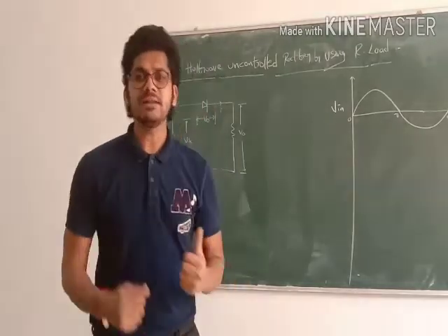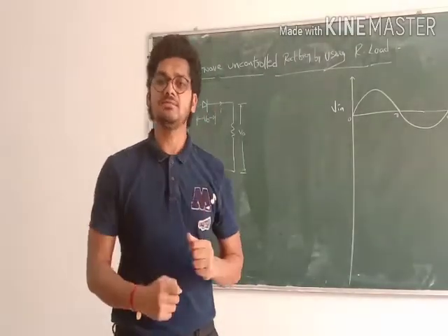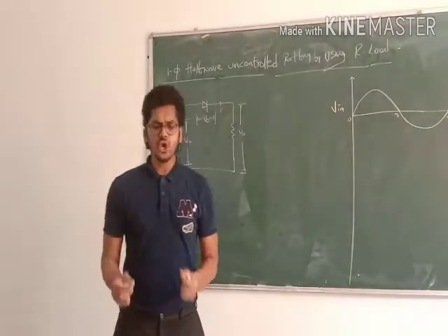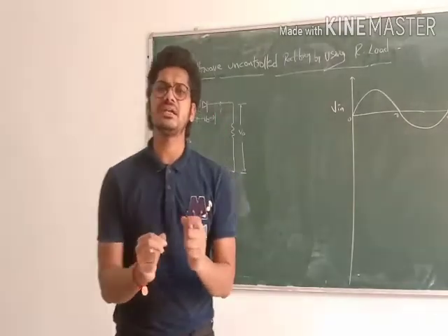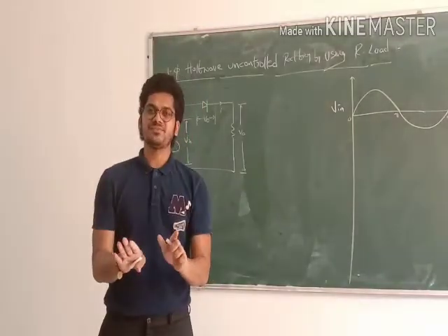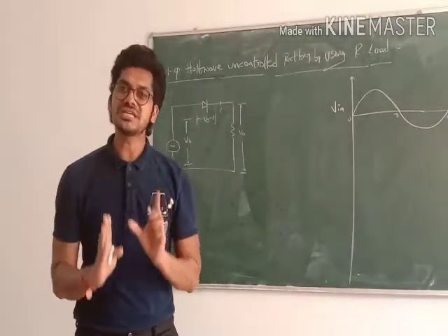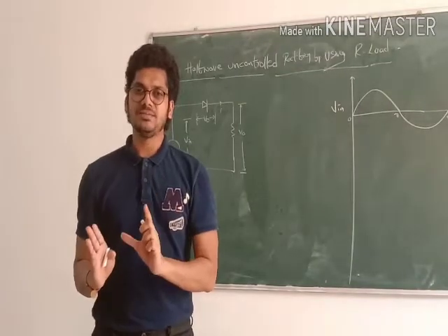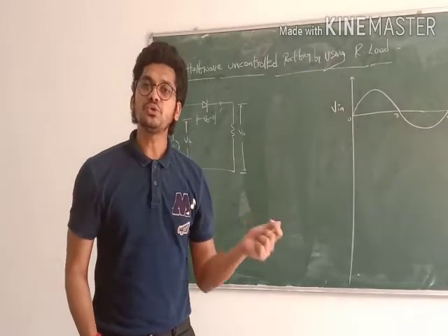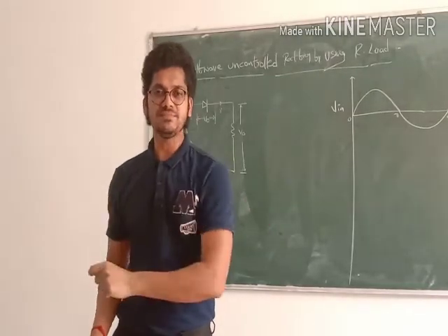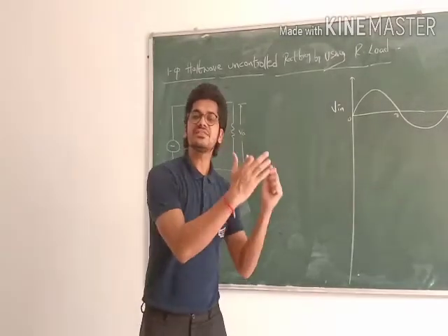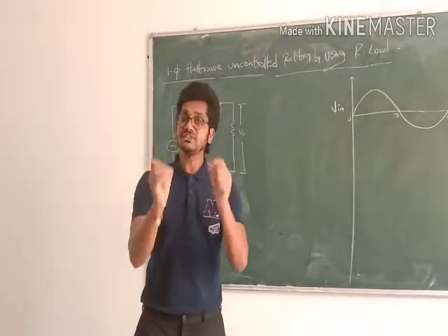It has an anode terminal, a cathode terminal and the gate terminal. The third one is MOSFET, BJT, IGBT, IGCT. Totally, advanced power semiconductor devices come under the controlled switches. Okay. Today our topic is how we are going to design the mobile charger, how we are going to reduce 230 volts AC into 5 volts DC, and how our mobile charger works, how the charger converts AC supply into DC supply with different loads.